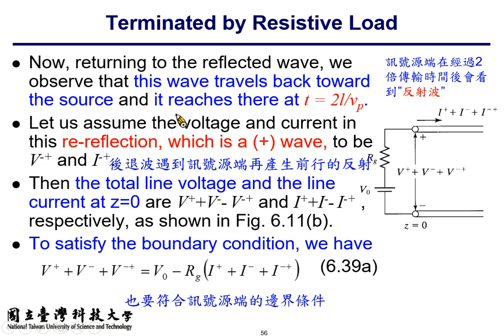For a passive component or passive transmission line, the reflection coefficient is smaller than 1. So eventually the magnitude of the reflection signal approaches 0. Now you will have a converged solution.